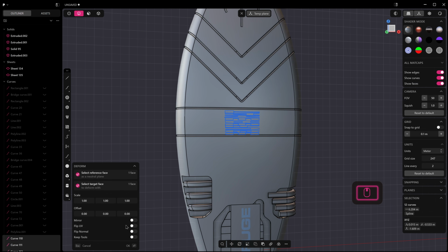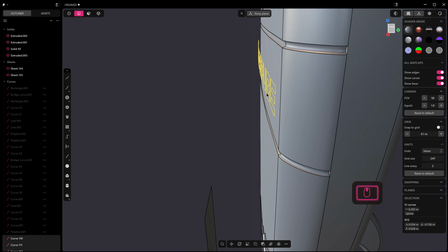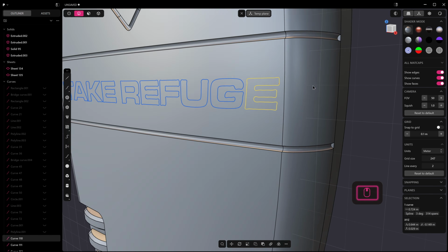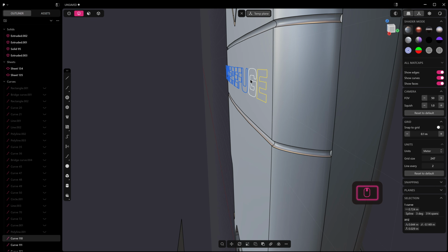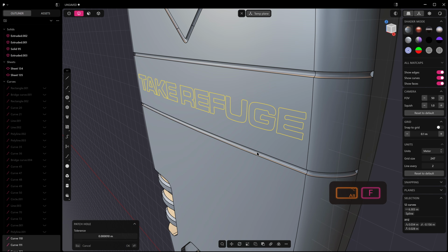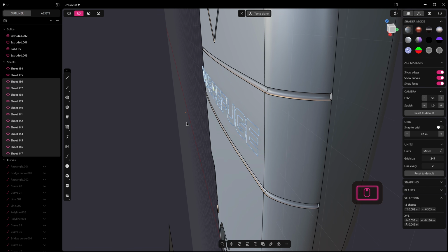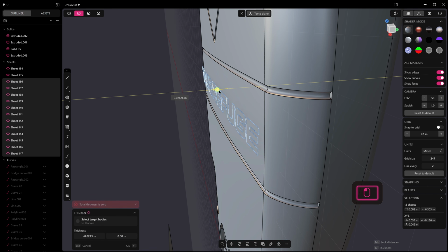But it's all wonky because it's gone a bit sideways. So we can hit flip UV and we can hit mirror. And there we go, we've got it on there now. These are all a little bit off kilter, and you'll notice that they don't look like closed loops. So we actually have to patch these one by one, or select all of them and hit patch. And now we've got all of these sheets, which we should be able to all thicken.